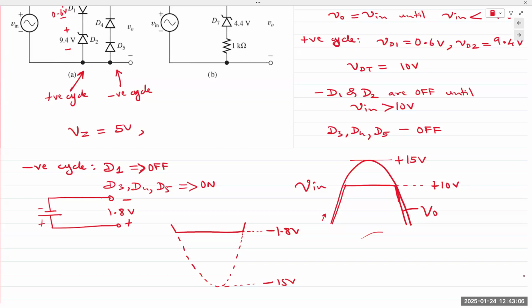If voltage exceeds in either direction, the Zener is gonna sink more current through itself and keep the output voltage constant. So if you have a Zener diode of 120, 130 volts, one in the positive direction, one in the negative direction, in parallel, surge protectors would have two of them. Yes.